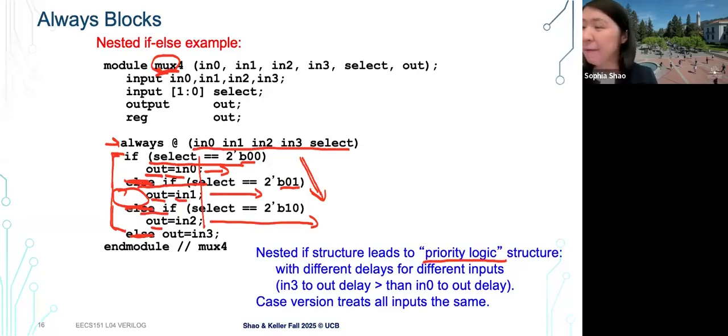But here, everything is still combinational. So there's no clock in the signal. You look at what we have, there's no clock. We're still talking about combinational logic here, right? So that's why we haven't seen the clock positive edge there. When you see the positive edge, that's basically when you start doing actual sequential logic. That's a good question. Any other questions?